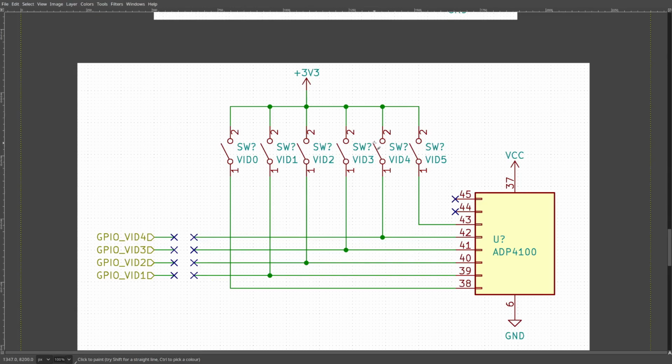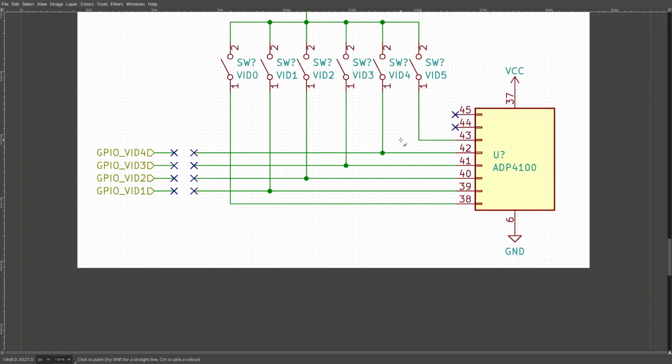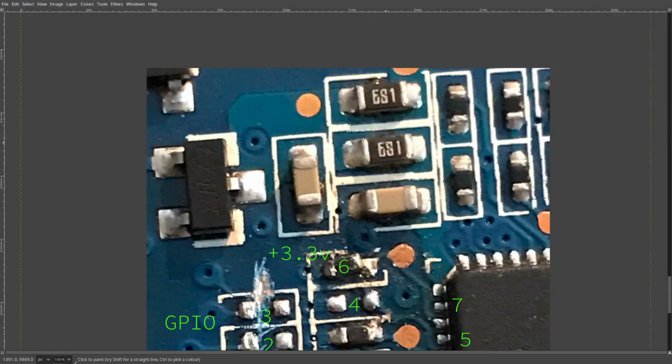And we have to wire in multiple switches, which can suck. But this is the point where I would say on certain controllers, you can simply set up your VID such that you get either 1.2 volt VID or 1.4 volt, and then use feedback mods from there to basically get your range in between. And you can get a pretty good range that way where you have one switch, one feedback mod, and it's not too bad to do. And this is how you get around a lot of the issues on like over voltage protection. You can do that as well in there.